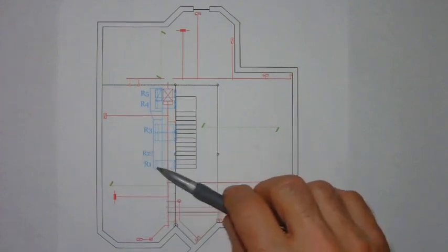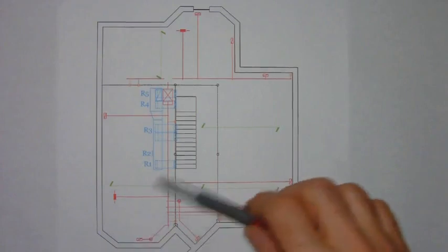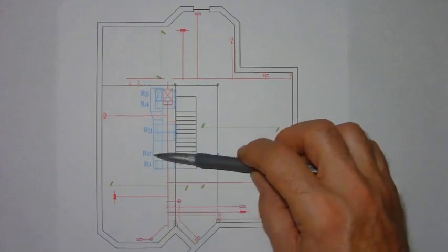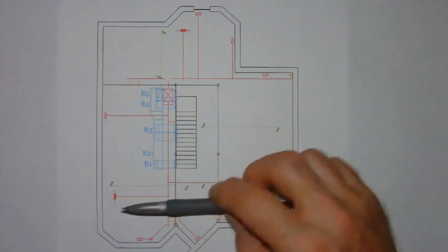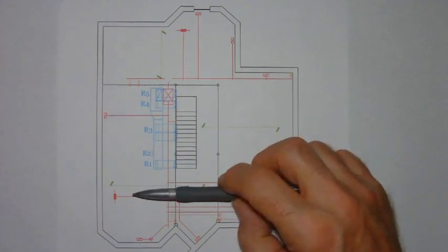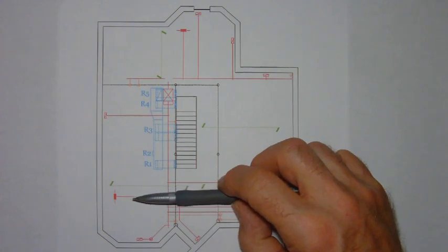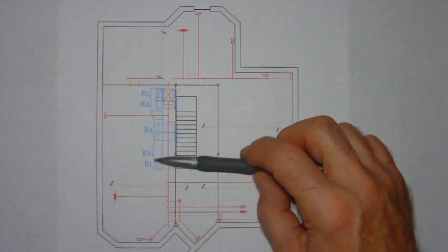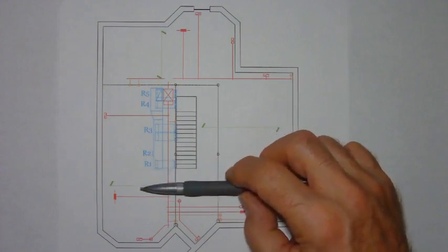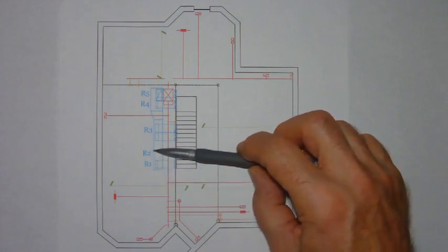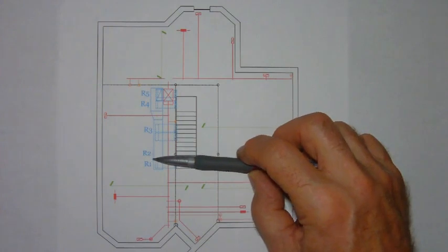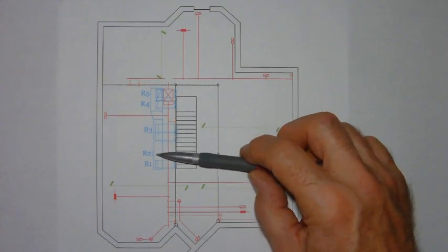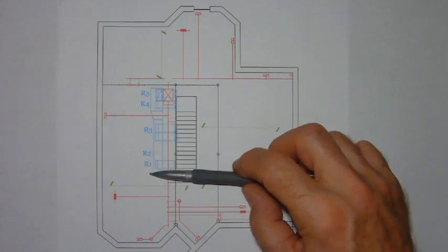Now, in terms of our basement return air, because the basement's unfinished, you are allowed to place a fitting directly on the side of the duct, and that fitting would simply, for lack of a better term, create a hole in the side of the duct that allows for air to return back to the furnace. You will have to install a damper in this fitting to help control the different required airflow rates between summer and winter.